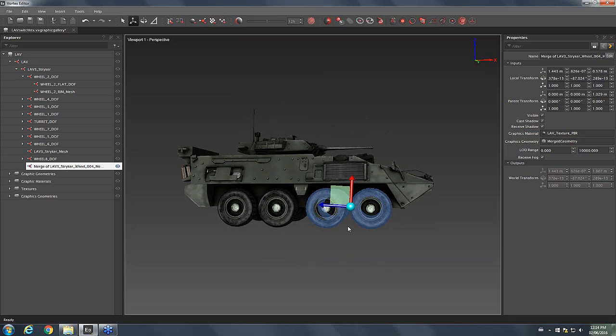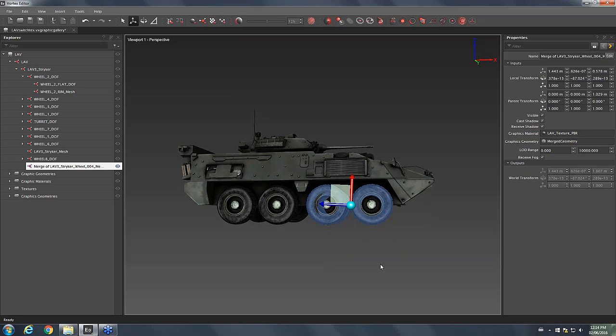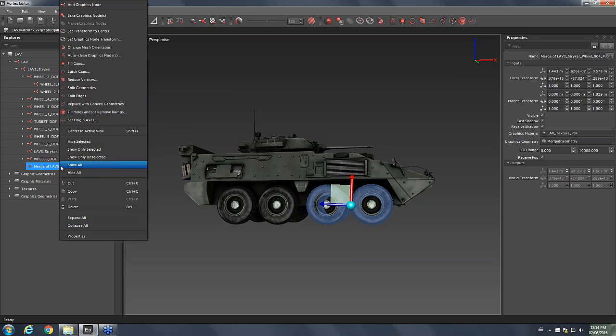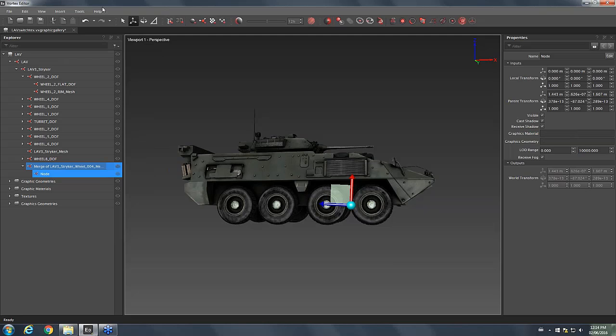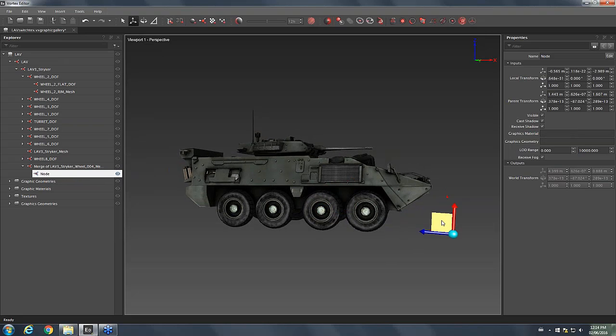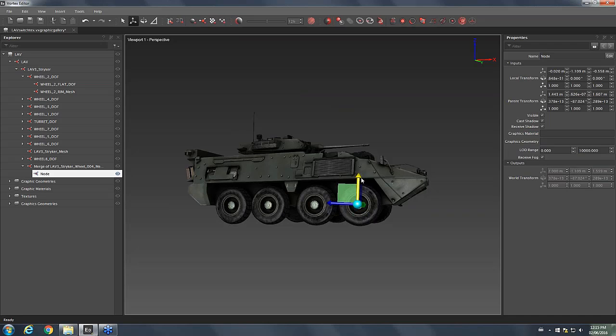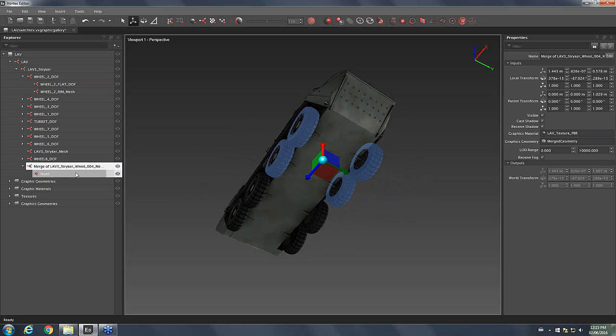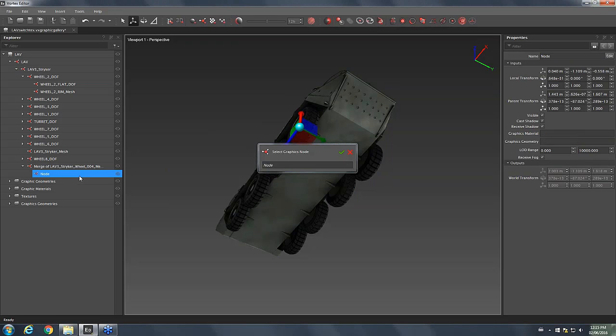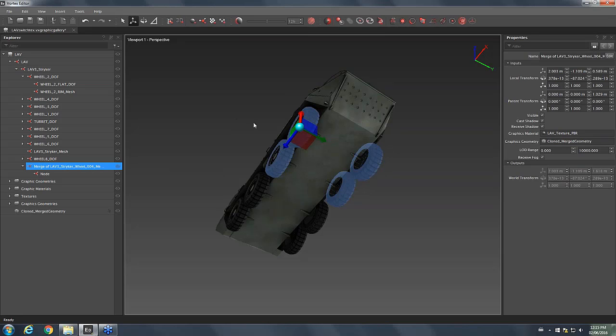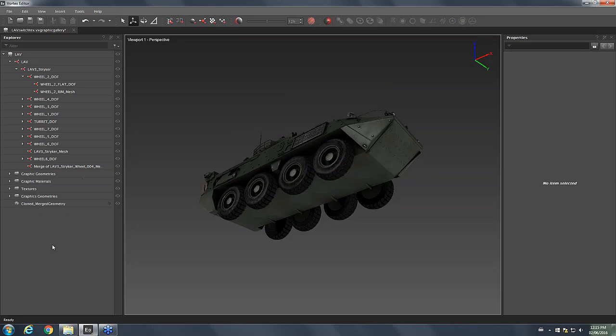Now let's say that I wanted to have a transform in a wheel, for example. There's a way to do this by adding an empty node to the model. So I grab it, and what this does is just add an empty node, which I can place anywhere. So I'm just going to use the bake again to remove all the transforms. So it's there. I'm going to place it wherever I want. So let's place it, for example, here at a rough position like this. Now my transform is at the middle, but I really want it to be there. So what I can do is use the set graphic node transform here, and I'm going to select another node, and then the transform is going to be moved to the new position, and then I can just go back to my original node and delete it.